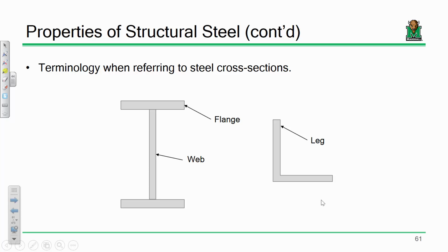Global buckling is if you have a column in a building and you push it and the whole thing bows out. Local buckling is instead of the whole column buckling out, maybe a flange crinkles or a web crinkles. Those notes where it says C are saying that the flange or the web might crinkle when subjected to compression. The C is for compression, the V is saying it might buckle in shear, and the H is saying you might have a local buckling issue for bending and things like that.